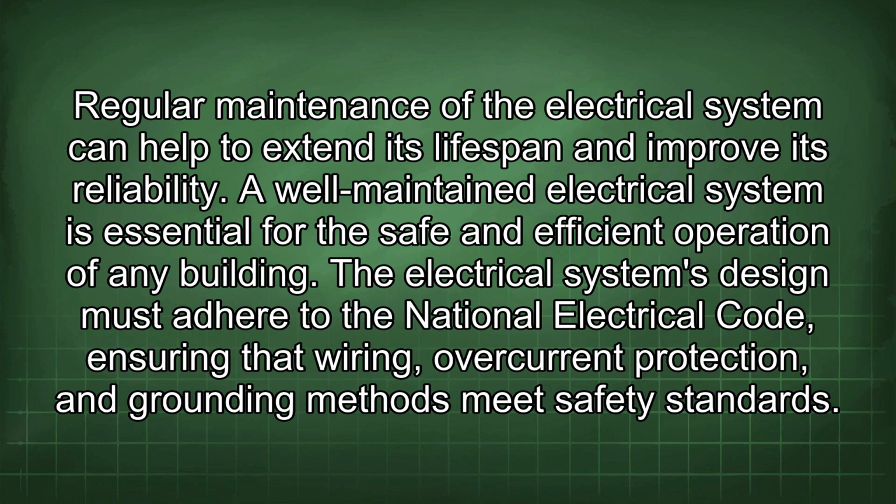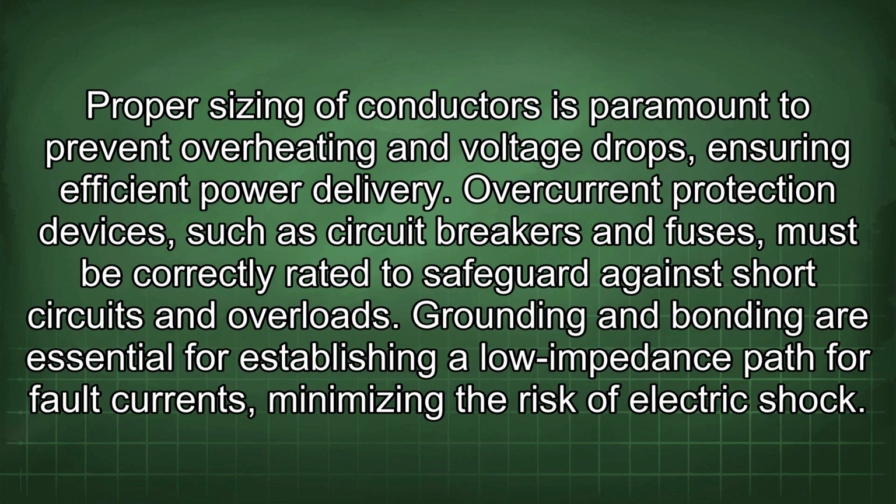safety standards. Proper sizing of conductors is paramount to prevent overheating and voltage drops, ensuring efficient power delivery. Overcurrent protection devices, such as circuit breakers and fuses, must be correctly rated to safeguard against short circuits and overloads. Grounding and bonding are essential for establishing a low impedance path for fault currents, minimizing the risk of electric shock.